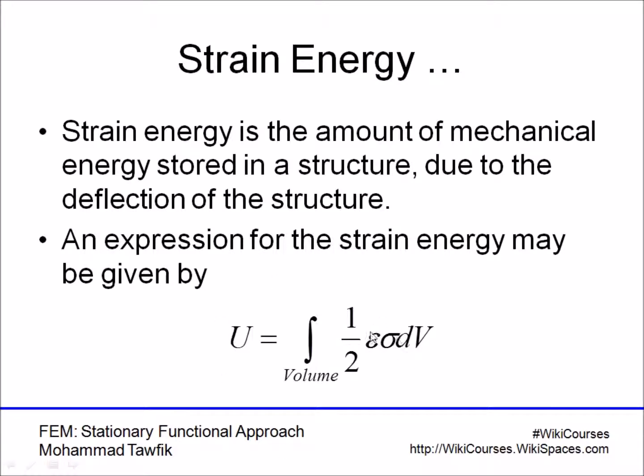Notice that using the constitutive relations, we can always remove the stress or the strain and represent it in terms of the other. So, for example, in a simple one-dimensional structure, the stress would be the modulus of elasticity times the strain. So this term becomes half E epsilon squared. Or we can say that the strain is equal to the stress over the modulus of elasticity, so it becomes half stress squared over the modulus of elasticity. It doesn't matter, but in finite element analysis, we usually use the strain squared representation.